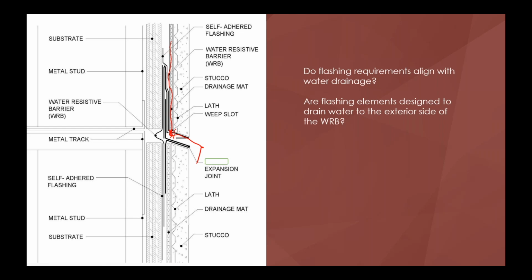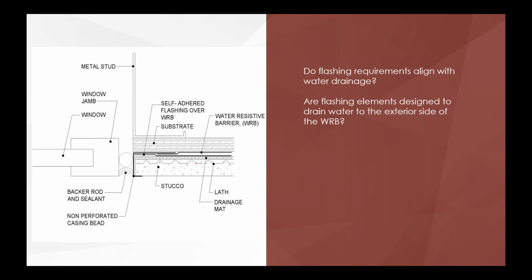Everything is properly shiplapped. This accessory is being run at the same time the water resistant barriers are run, and this way I can properly shiplap everything in. If all your water resistant barriers are up and now you're going to start putting in your trims, you're going to be at a disadvantage. You need to put a lot of your stucco accessories in with your water resistant barriers at the same time so they're properly shiplapped.